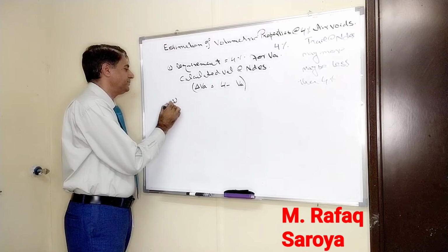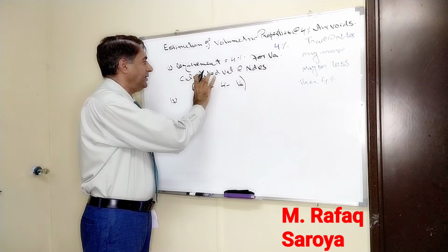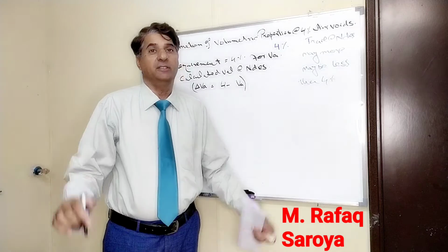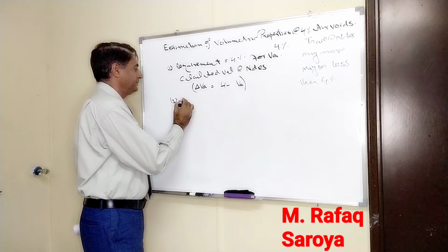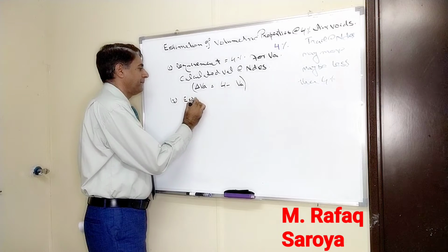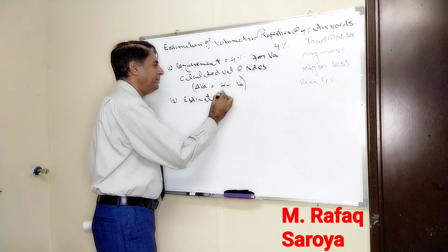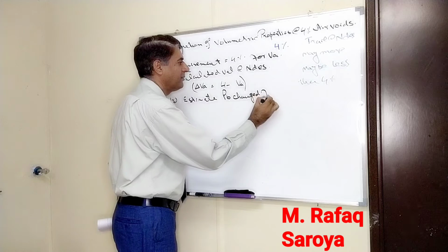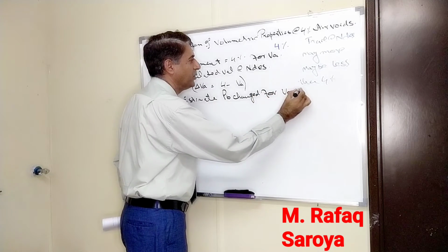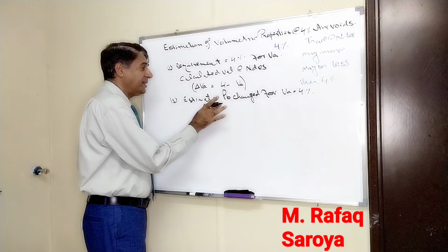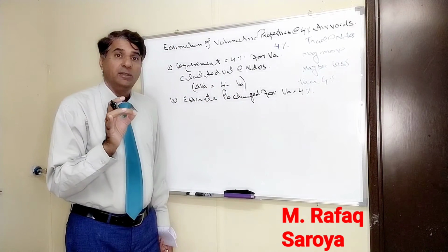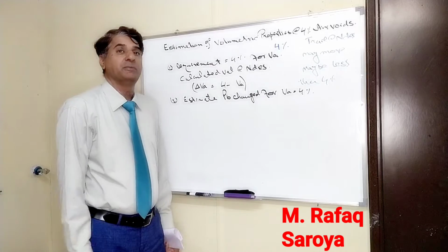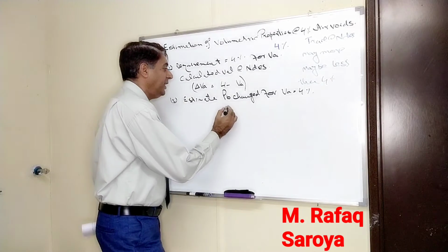Second point, if this VA needs to be brought to 4%, all the properties will change. So here we will estimate what? PB change for VA equal to 4%. What do you mean by this? Here PB means our bitumen percentage. When we have to change our air void to 4%, its value will also change. How much will its value change? It is given by this formula.